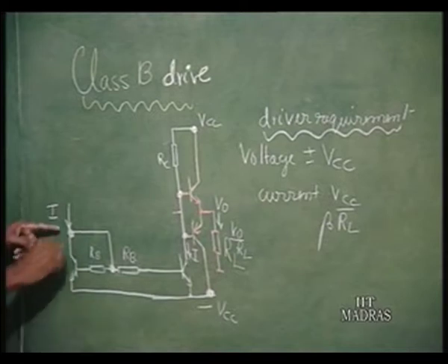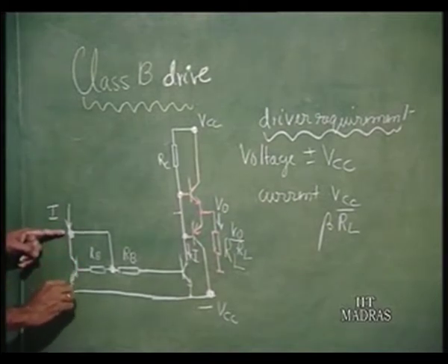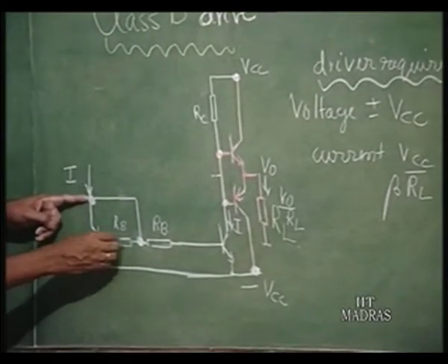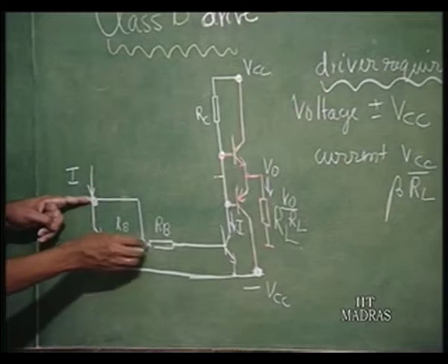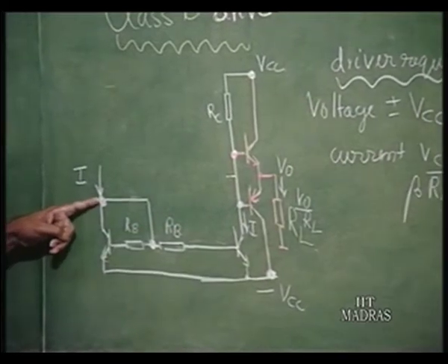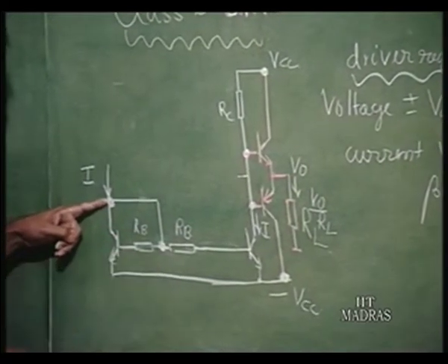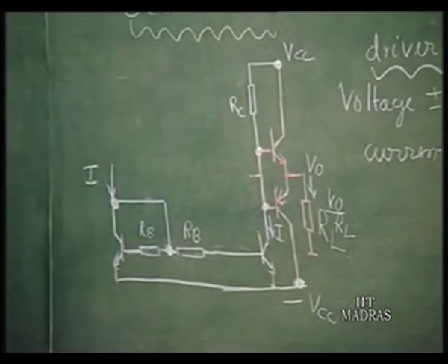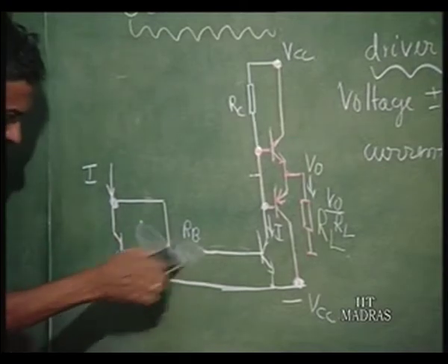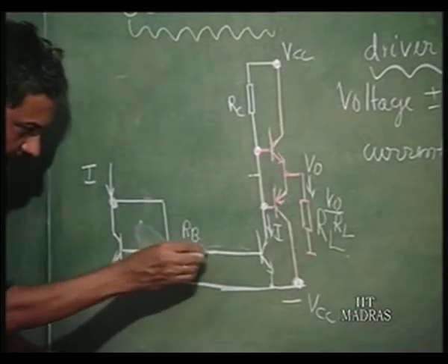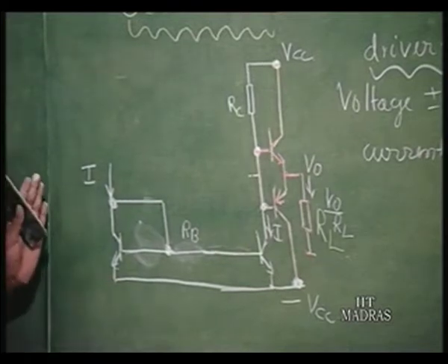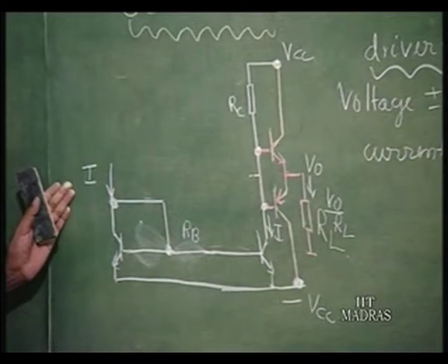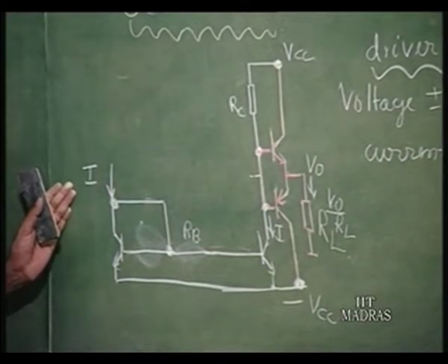You can see this. This is a transistor connected with the collector normally connected to the base as a diode. Suppose you do not put this resistance, it will be just this, it is a current mirror. I will explain to you why such resistance is put presently. If you do not put a resistance, it is a straightforward current mirror. If there is I here, there is I flowing there, current mirror. This we had discussed earlier.